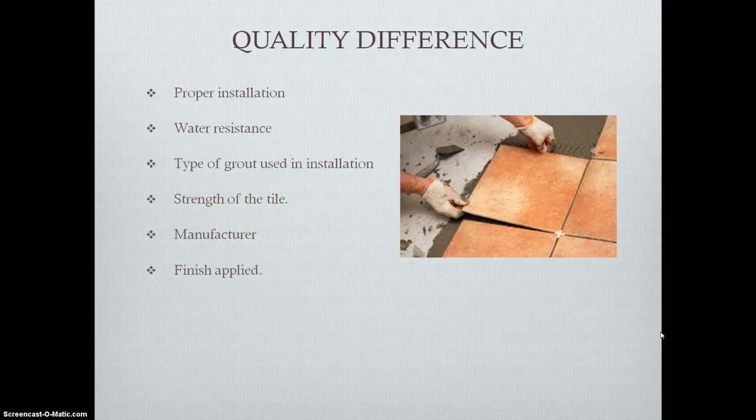One of the main differences between tiles that determine its quality is water absorbency. There are 4 different categories of water absorptive qualities of tiles: non-vitreous, semi-vitreous, vitreous, and impervious. Non-vitreous absorbs 7% or more of its body weight in water. They are suited for indoor use only and considered to be non-frost resistant.